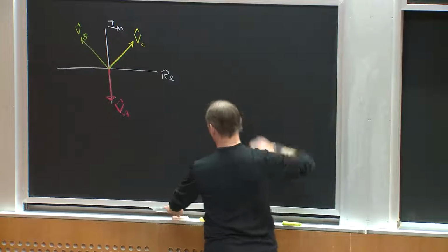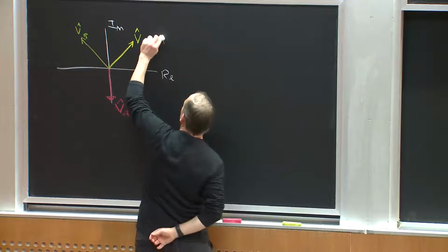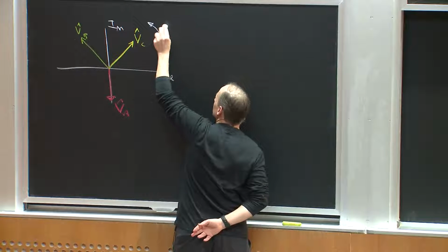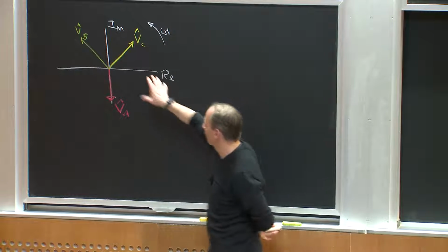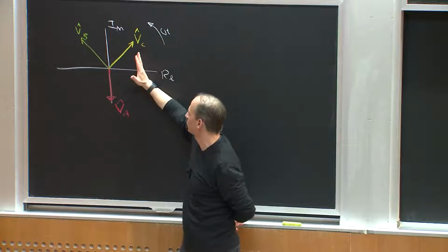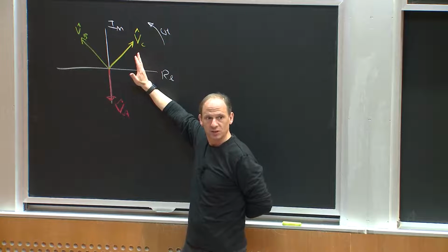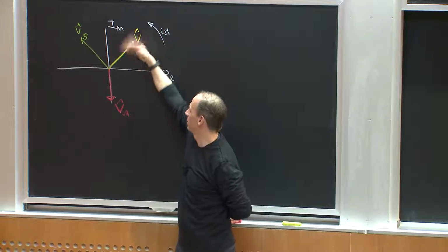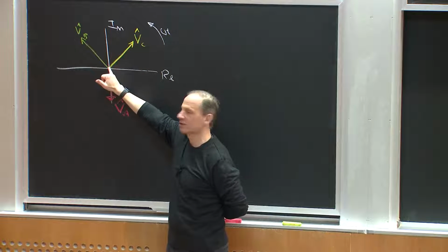Then when I multiply by e^(jωt), I'm essentially rotating it by an angle ωt. To get the instantaneous time values, these phasors rotate and I take the projection onto the real axis. At t equals 0, sin(ωt) is not rotated and just projects to 0.